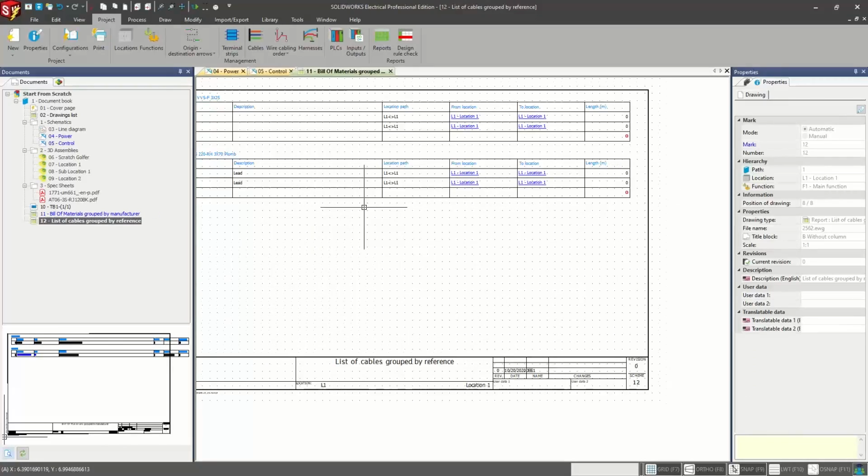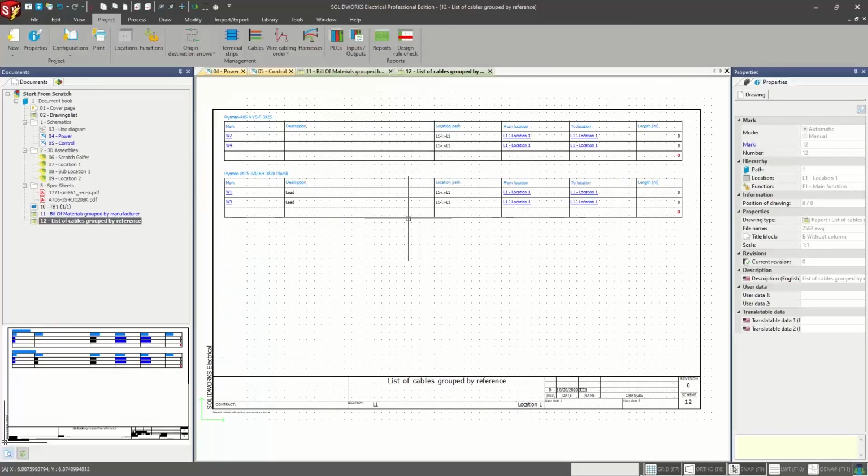We can also take a look at our cables that we used for this project. We get our to-from information, maybe the description from the cable, what kind of cable it is directly. And if we connected to the 3D side for wires and cables, we can capture a length. One thing I will note also, if you are running wires, you have to route in 3D in order to capture the length.